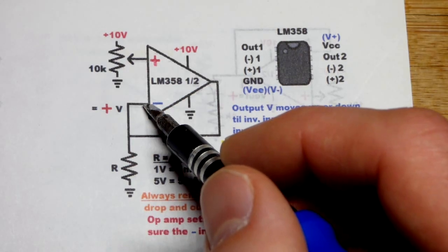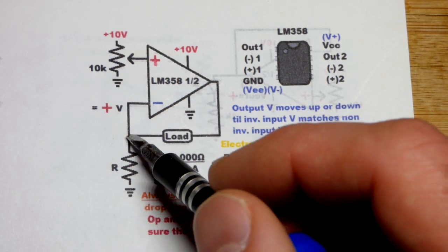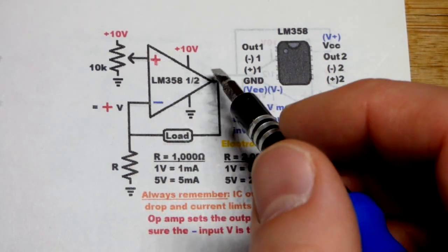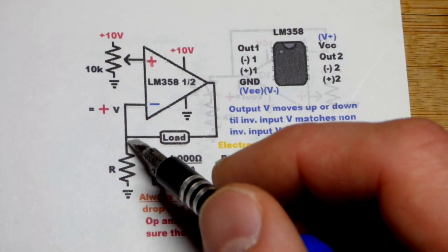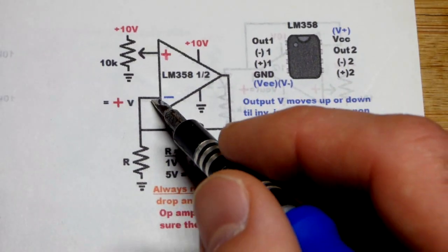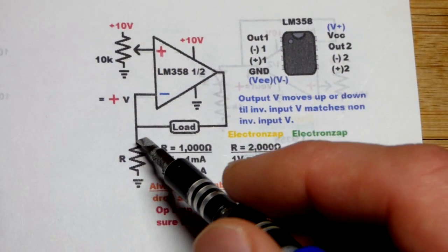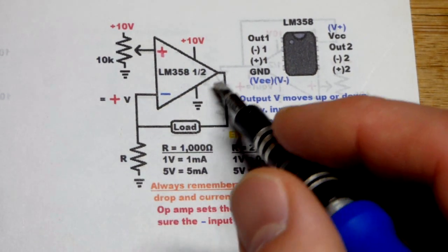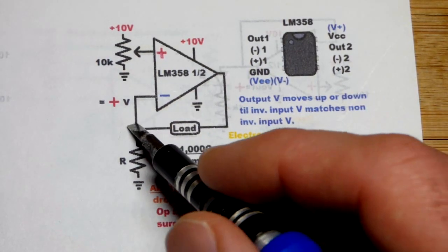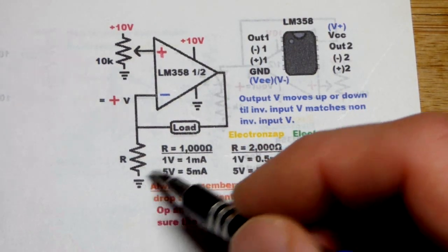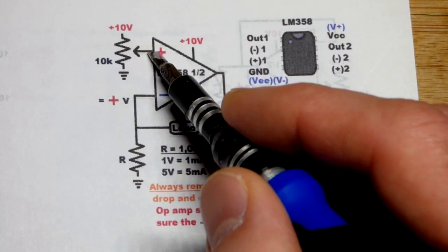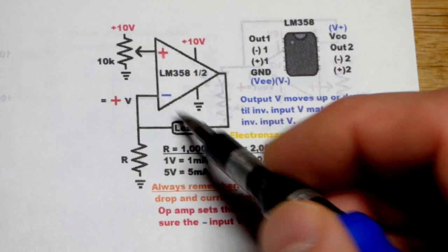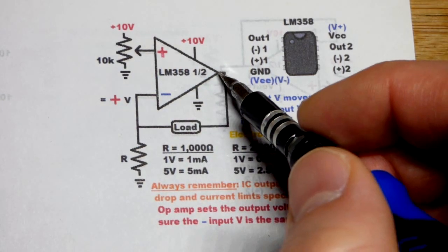Now, the reason we need that voltage for the current is this resistor right here. So remember, the inputs don't let current in or out. This is the current path right there. We got a resistor from the inverting input to ground, and therefore there's going to be a current that flows. That current has to come from the output, go through the load, and then go down to ground. So if we set 1 volt at the non-inverting input, then we're going to have 1 volt at the inverting input. Again, if the load needs 2 volts, that'll be 3 volts at the output.